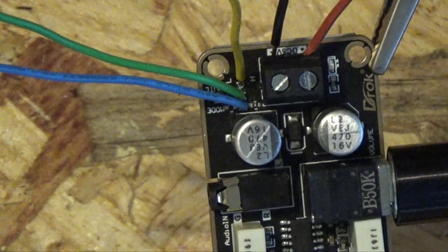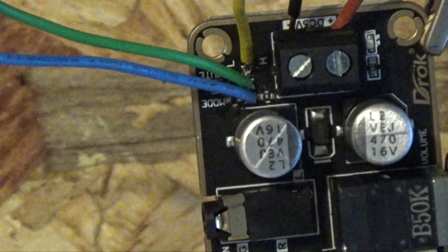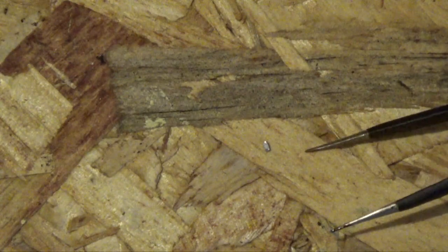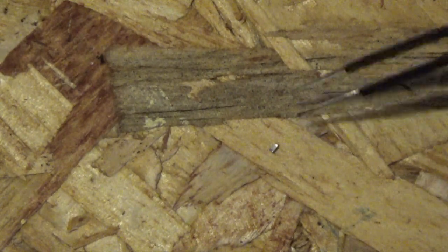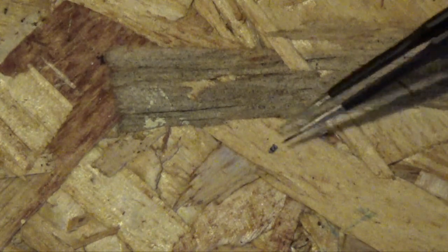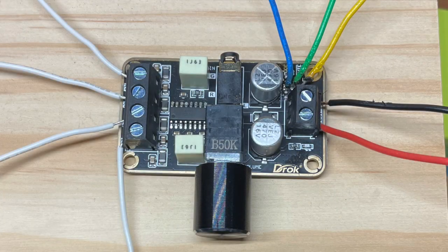The 0 ohm resistor acts as a jumper connecting two pads together. So it's like a jump wire that creates a short. If you remove the 0 ohm resistor, then those two connections will be open. I'm an amateur when it comes to board work, but I was able to remove the 0 ohm resistor here. It's a very small component, and you can see the damage left at the wires here. Despite this workmanship, the board works and the pads are now exposed.